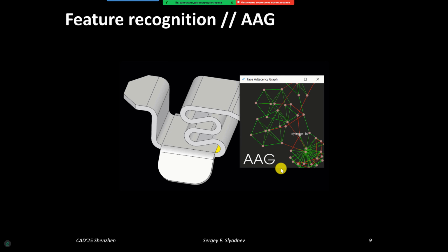For a boxy shape, you will have these 6 nodes and 12 edges, and information about the dihedral angles, but that's not a unique descriptor of the shape. It's a supplementary data structure that we use, but we still have the boundary representation to work with. Both data structures live in memory, the boundary representation and the AAG, and there is a link from the AAG to the boundary representation to query geometric properties. Does that answer your question?